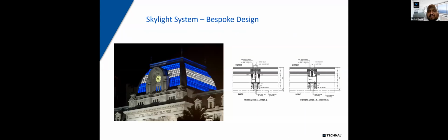Here's an example of a very famous museum where you have extended skylight. You have vertically moving skylights with horizontal glass features on the top as well. So what we did here, and in all these designs shown here, we use what we call the add-on system. Steel behaves like your primary structural element, and the aluminum system sits on top of it. But what's important to know, these are interbracing systems. So your mullions and rafters go within each other, so you get complete clean lines when your panels are intersecting. And of course, these are all drainable systems.